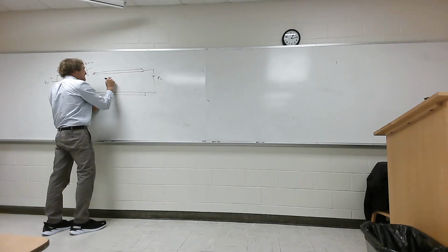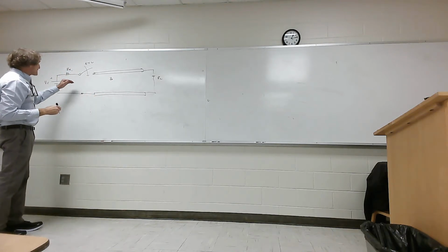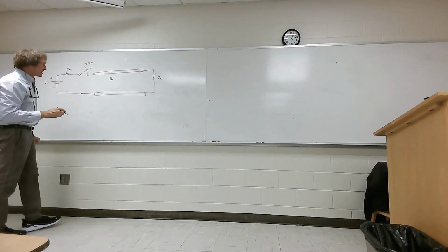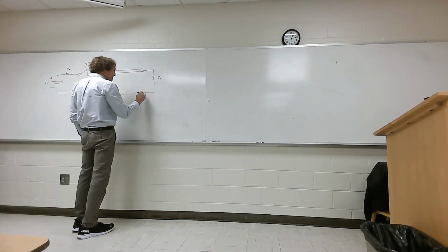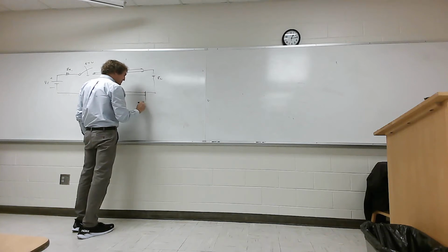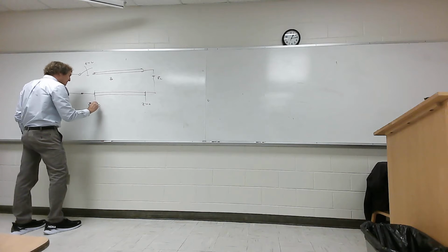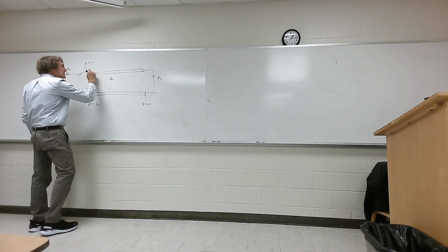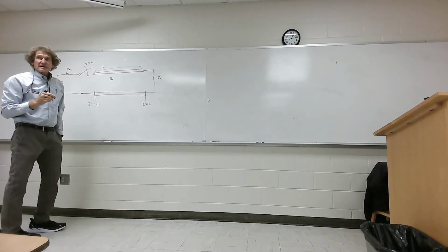And the transmission line has a characteristic impedance Z0. Now there's a couple things we're going to do. We're going to get both the current and the voltage at any point in the line. Normally what they'll do is they'll put this at z equals 0, but it's not necessary. This would be z equals minus L here, and it has a total length of line L. And they're going to go ahead and get the bounce diagram.